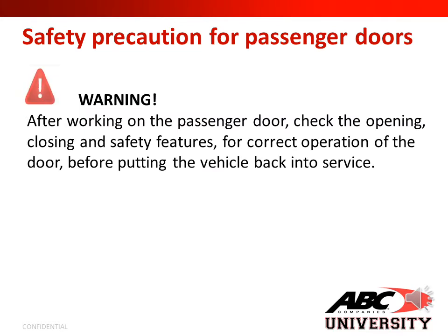Safety precaution for passenger doors. Warning: after working on the passenger door, check the opening and closing safety feature for correct operation of the door before putting the vehicle back into service.